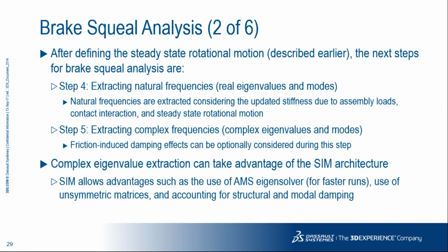And in continuation to the brake squeal analysis, the preceding steps determine the initial stresses in the model and the steady state braking conditions. Here the real eigenvalues and the mode shapes of the model are extracted, and in this procedure the tangential degree of freedom at the contact nodes, at which a velocity differential is defined, is not considered. The set of eigenmodes provides the subspace for computing complex eigenvalues, which can be done in the next step.